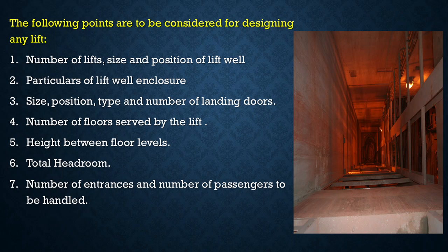Number of lifts, size and position of lift. So how many lifts you are going to provide, what is the size, and how you are going to position it. This is the first point you have to consider. Particulars of lift well enclosure.